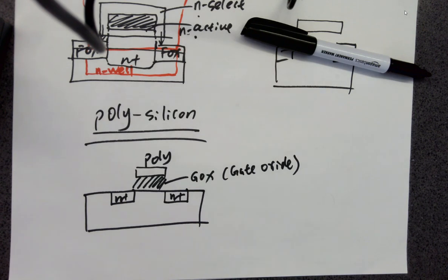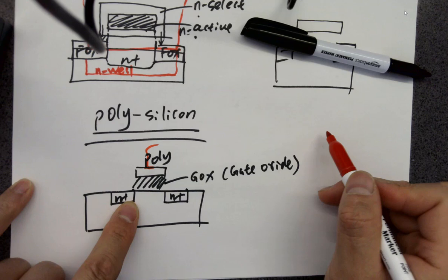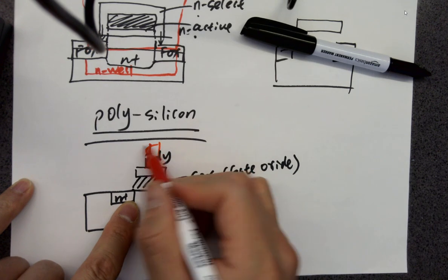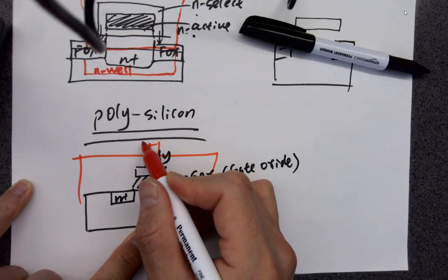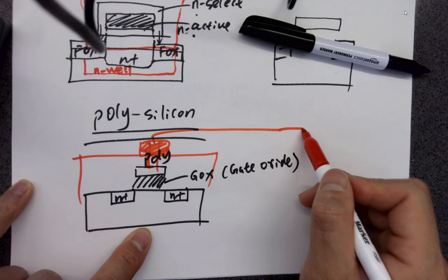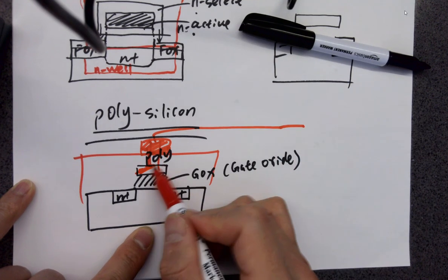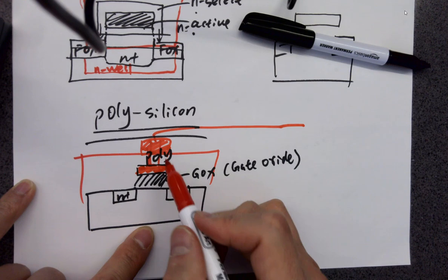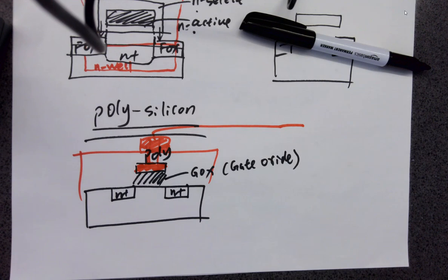So whenever you have to connect the gate to something at a longer distance, you want to drill a hole to the top, to metal one first. Here's the oxide layer. Right, here's metal one. You want to connect to metal one first, and then use metal one to route it, instead of directly using the poly wires to route it. It's a pink gate color. It's a pink polysilicon layer, and you don't want to use this one for longer distances.